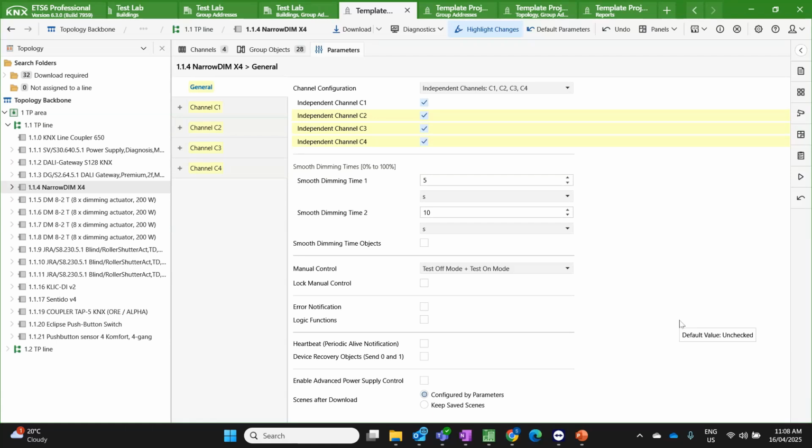So the next part is customer scene management. Now, a real beautiful part of KNX means that not only do you set scenes with global devices or any of the three ways we've discussed, but we can also save scenes, which means once you've left the customer with a scene, they can call that scene, individually adjust it from other switches or visualizations or other things, get the scene the way they like it, and then it's usually a long push on that same button,